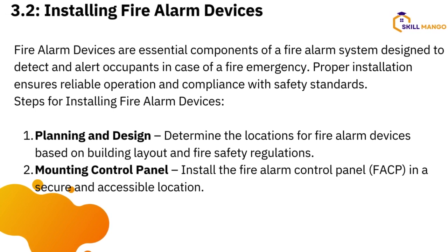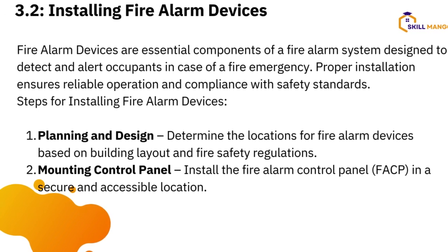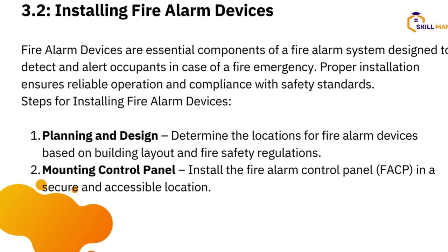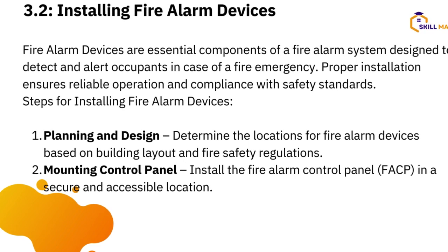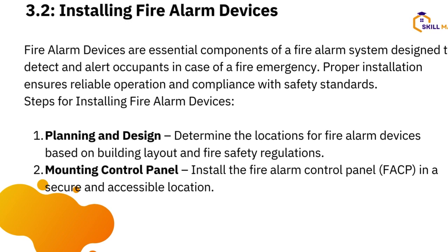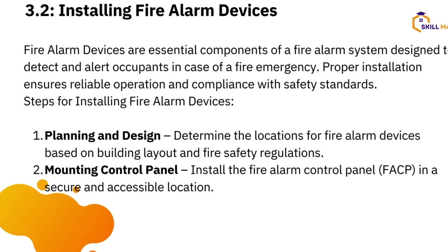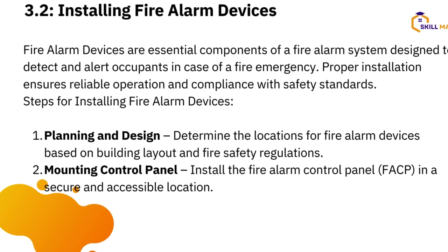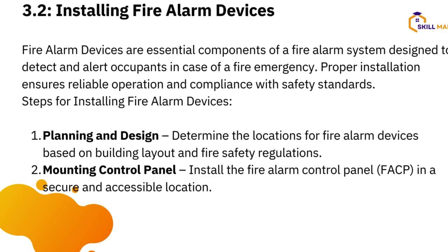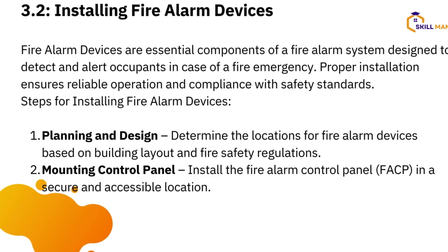So this is very important. We have to know this as a technician, as an installer, as an integrator. So we have to plan our site properly: the cable layout, the kind of cable we are running, the route, and how to ensure that the pipes are interconnected because of the loop we are going to be doing, the kind of cable, the topology we are going to be using. This is very important. That's the first thing to do.